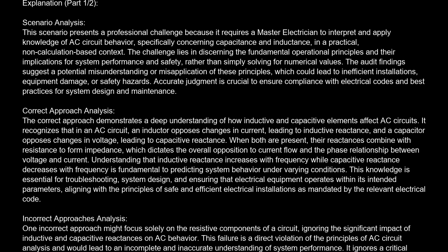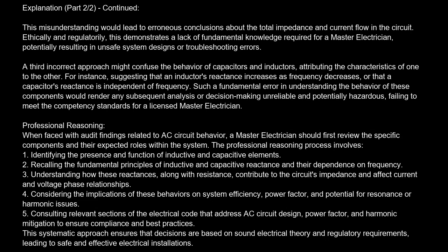Another incorrect approach might incorrectly assume that inductive and capacitive reactances are additive in a simple arithmetic manner, without considering their opposing phase relationships. This misunderstanding would lead to erroneous conclusions about the total impedance and current flow in the circuit. Ethically and regulatorily, this demonstrates a lack of fundamental knowledge required for a master electrician, potentially resulting in unsafe system designs or troubleshooting errors.